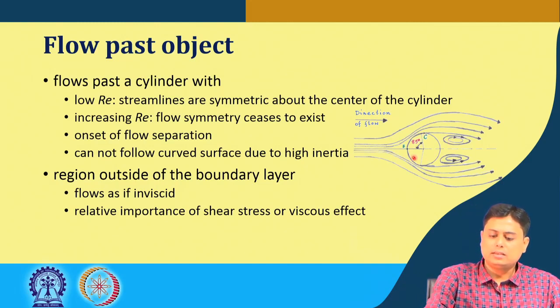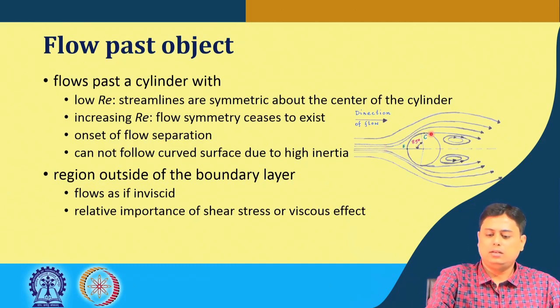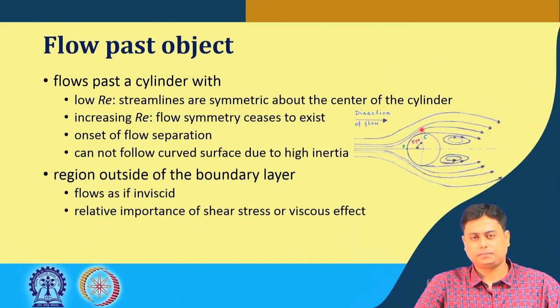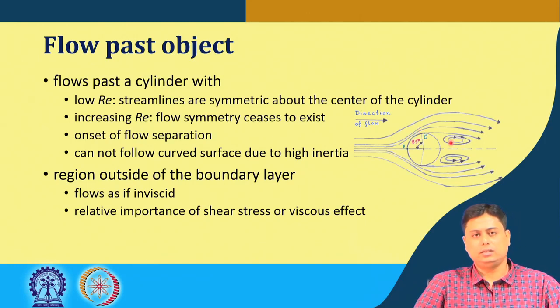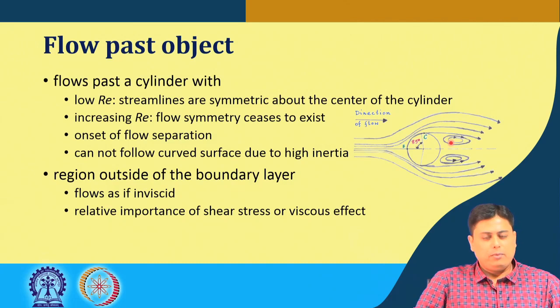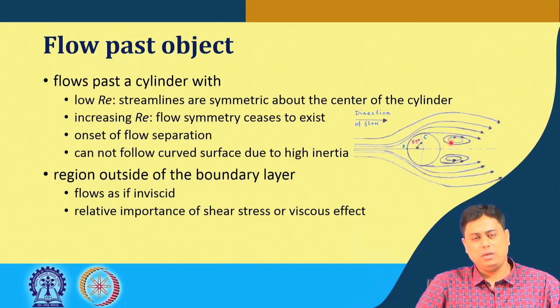Now, in this case, as I said, as the Reynolds number increases, this flow separation point is pushed back, and this wake formation region gets larger and larger. We will see that also in a couple of slides later. So, the point is, we have to understand this relative importance of shear stress or the viscous effect, and that actually gives us the measure of the boundary layer.